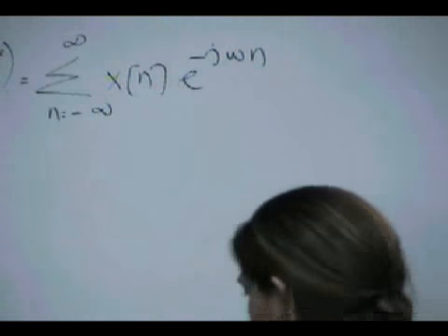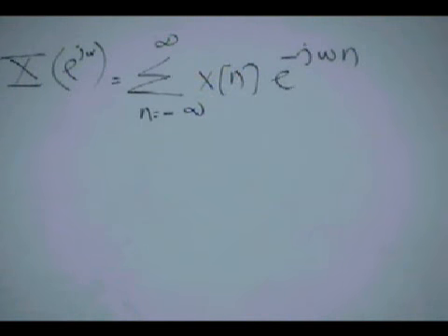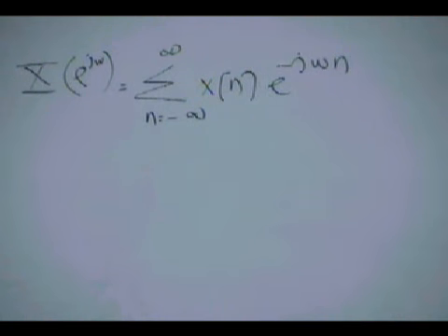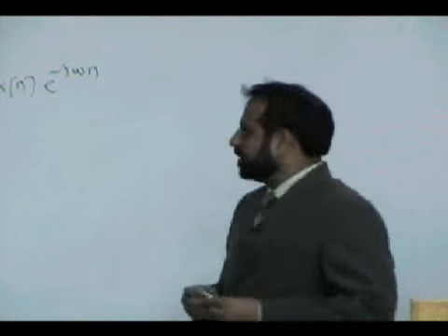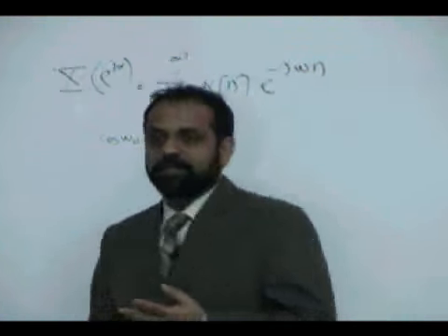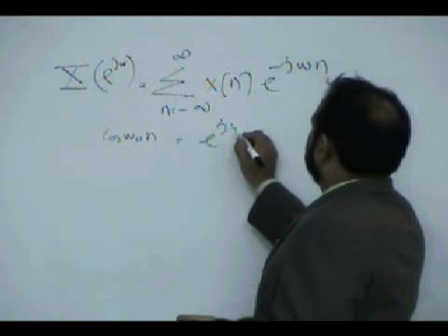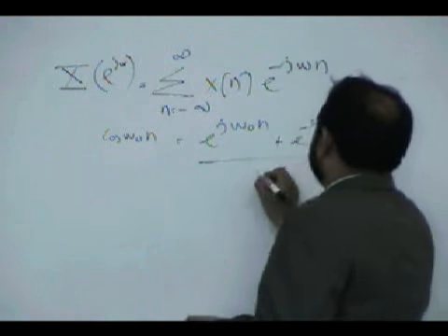And another way of conceiving the idea is that this is a transform which tells you about all the complex exponentials which are there in a signal. Okay, that's another easy interpretation, because you need a good interpretation. It tells you what all complex exponentials are there in the signal. For example, in cosine of omega naught n, I know there are two complex exponentials: exponential of j omega naught n plus exponential of minus j omega naught n, divided by 2.